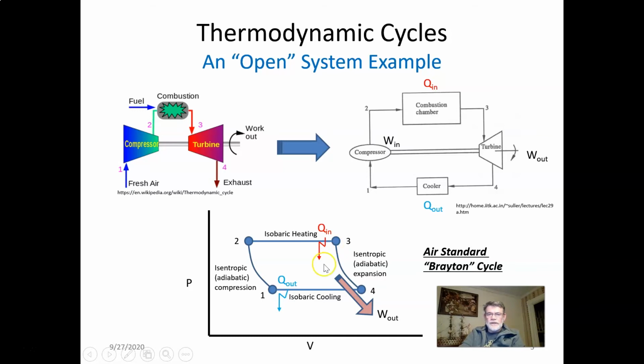To recap, here you have the compression, an adiabatic process, and it's the same as isentropic because it's reversible. Then you go to the heat addition in the combustion chamber, isobaric, same pressure. Then another adiabatic process during the expansion, and another isobaric process here for the heat rejection.